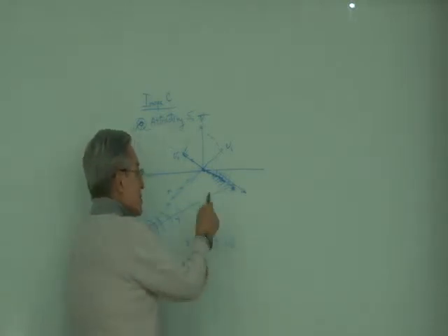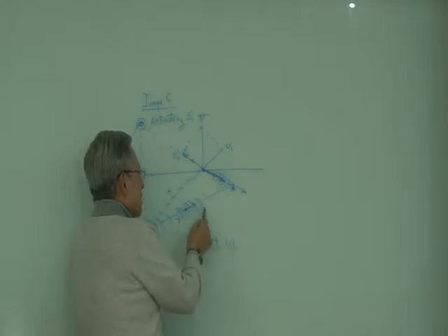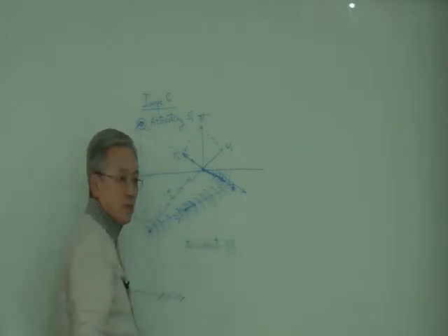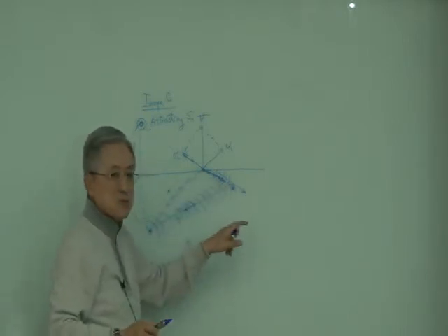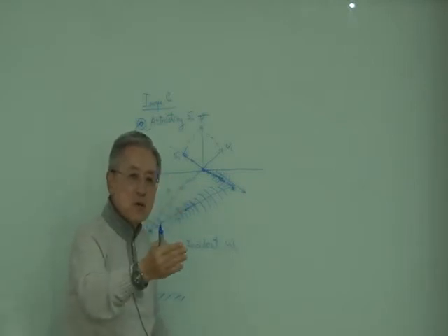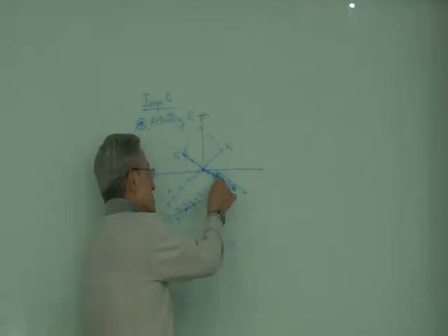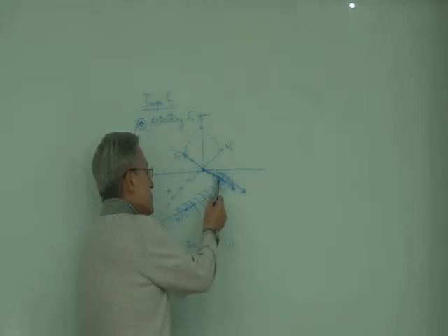You see that? But for the incident shock wave, if you look at the fluid particle, its direction is the same as the shock wave velocity. It's the same direction, but in this portion the direction of the acoustic wave or shock wave, which is moving in that direction, is opposite to the direction of motion of the fluid particle.